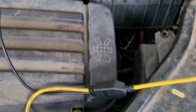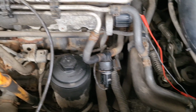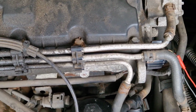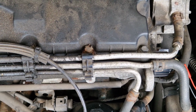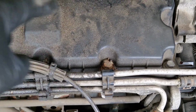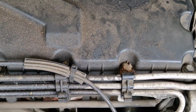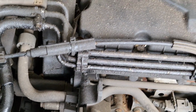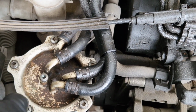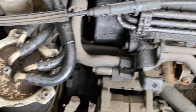So we put in a new bulb, and that fault code was rectified. Now the customer is looking for the injector, and once we open the rocker cover we'll see what the problem was. But anyway, it's starting since we serviced the engine. Since we changed the fuel pump, the non-starting problem has gone.